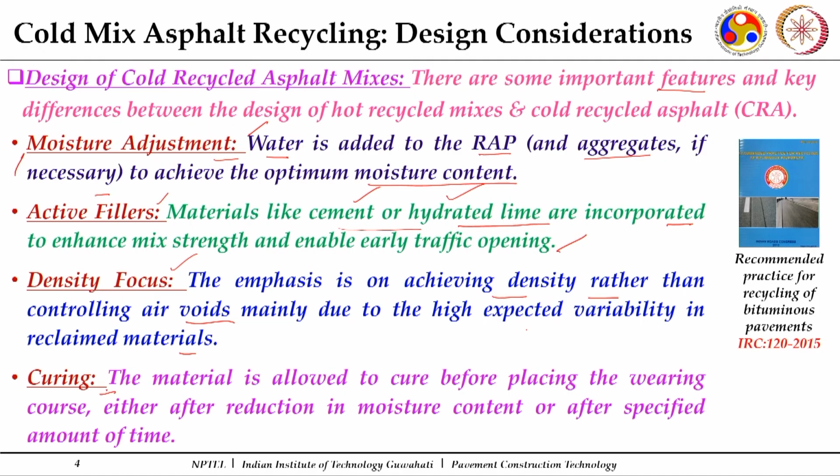Curing is another aspect which is usually not required in the case of hot mix asphalt. After, say, an overnight period, the surface can be opened for traffic, but here curing is an important aspect in the design of cold asphalt recycled mixes. The material is allowed to cure before placing the wearing course, either after reduction in moisture content or as specified.